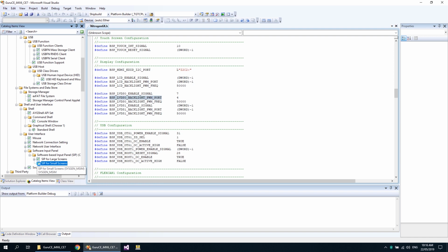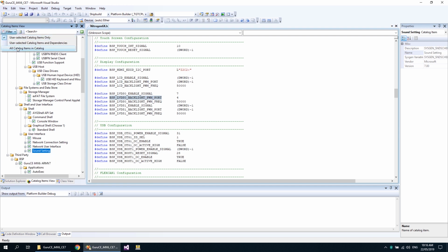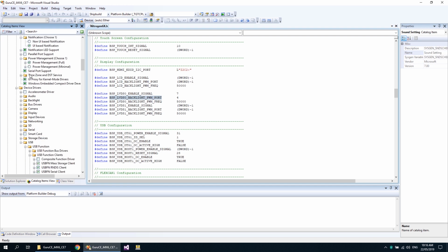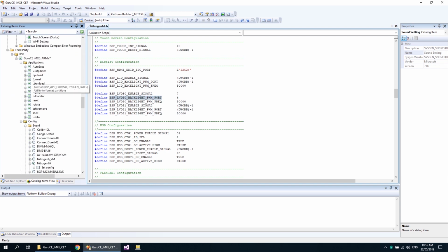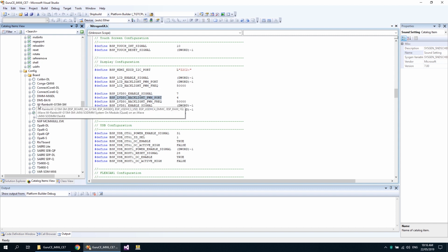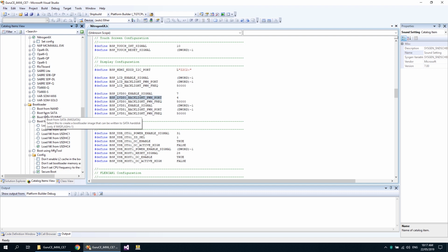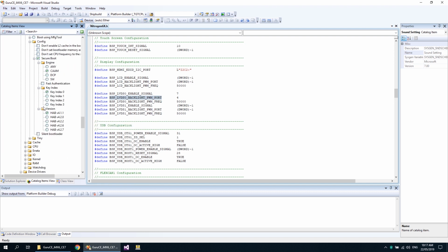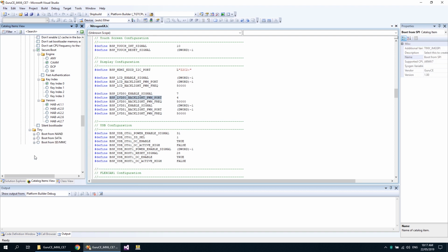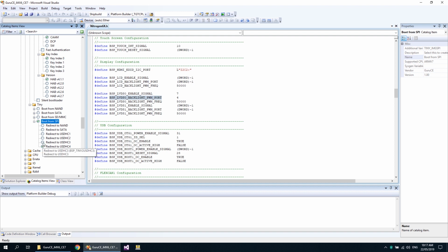Before we start the build, let's check we have everything set correctly in the BSP Catalog and we're not missing anything. We'll reset the Catalog filter to show all Catalog items and run through the selections again. We have all the applications we want selected, the correct board is selected, and the bootloader will be built for SDMMC. Also, the Nitrogen 6X is hardwired to boot from SPI NOR Flash, so we will use the tiny bootloader to redirect the boot medium to microSD on USDHC3.